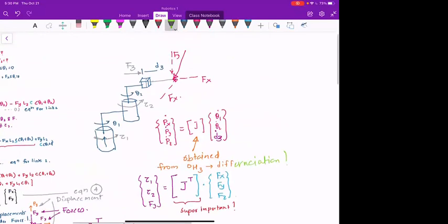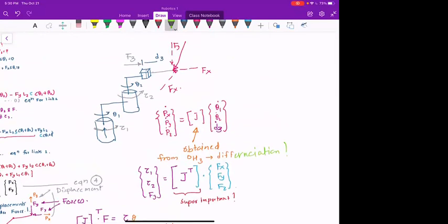So the idea here is, we are very comfortable with doing the forward kinematics. What happens in forward kinematics? In forward kinematics, finally we get 0H3 in this particular case. In 0H3, you are going to have 0R3, and you are going to have Px, Py, Pz.